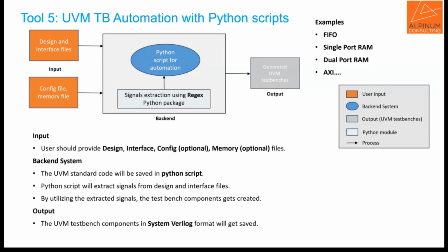Yeah. Okay. So in the next slide, what I'm going to show in more detail is the automated test bench. It is the Python generated test bench for the UVM, and it is the part of that model that incorporates the whole modeling and the strategy that was shown earlier. It is one of the integral parts of that flow where we have the test bench automation implemented.